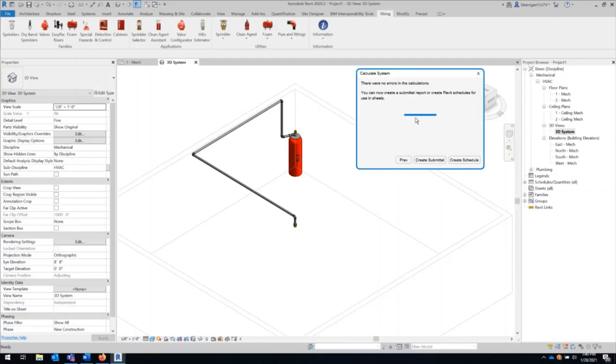So something you might encounter is that the pressure at the final nozzle is too low. You're going to want to rectify this by choosing a larger supply. So maybe we size up the container. Maybe we need more than one container. There's a handful of different errors you might encounter, and usually the design manual is a pretty good reference in terms of helping you resolve some of those. But if you're ever encountering a really complex scenario, you can always reach out to Doug or the digital team, and we can try to help you through it.